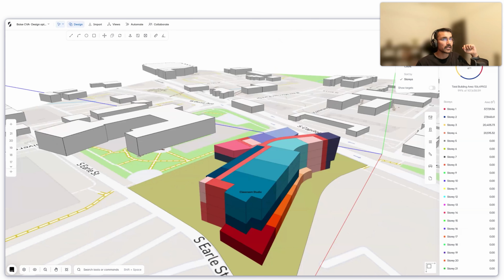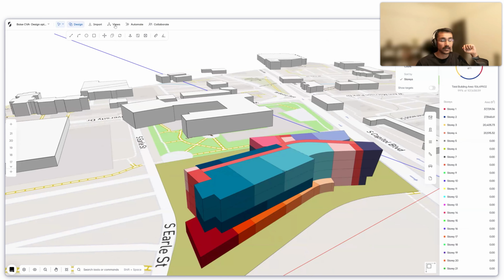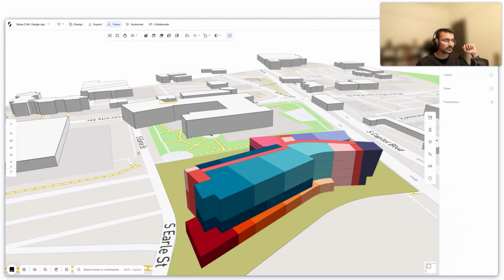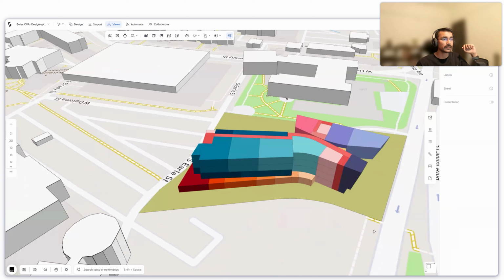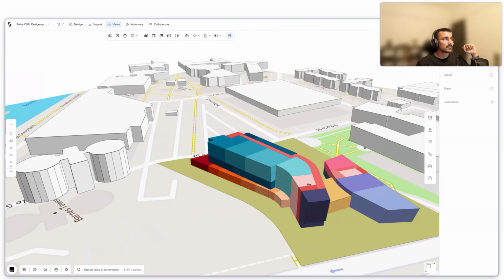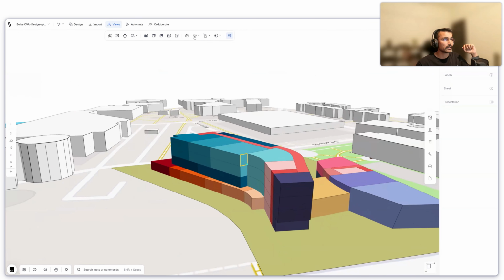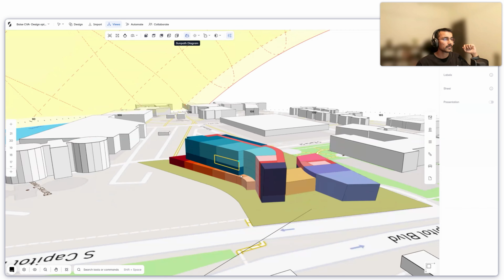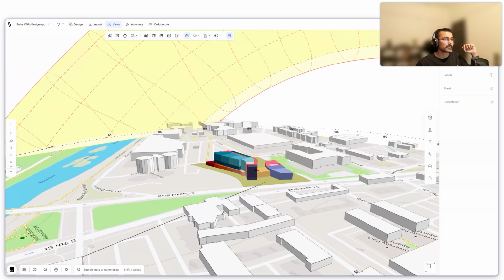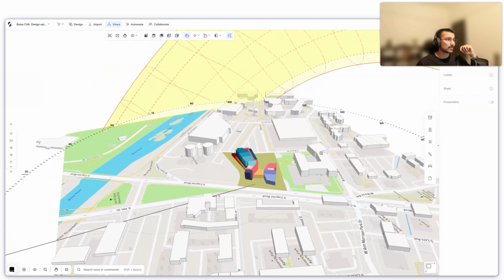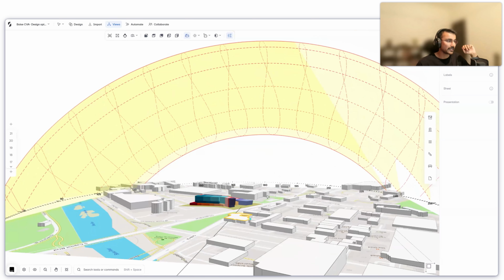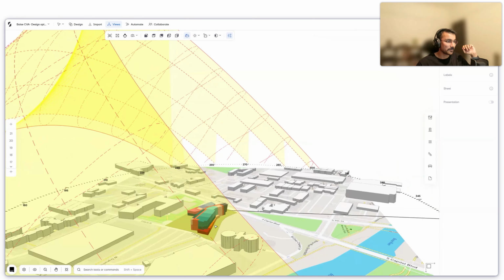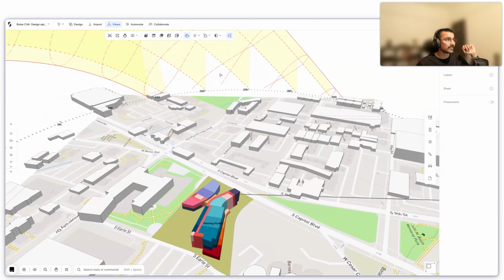Now the next thing which I would like to do is also verify the sunlight performance. We've been talking about having views, having glazing, but does that really make sense in Boise's climate and with the sun hours study over there, right? So the first thing I'll do is turn on the sun path diagram here. And just going to zoom out a bit so you can see the entire neighborhood and how low the sun actually gets as compared to where I'm from. India is, of course.